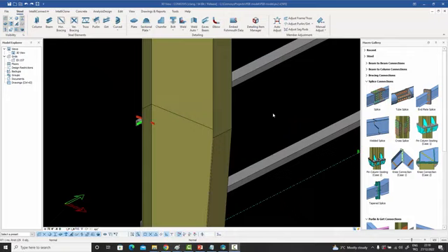for the creation of pre-engineered buildings. Now let's talk about another macro which is used in the pre-engineered buildings sector, and that is the tapered end plate splice. It's very common to have elements which are tapered, and one of them is tapered, the other one is straight, or both of them are tapered. And you need an end plate splice connection for such situations.